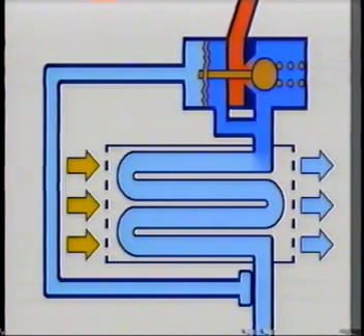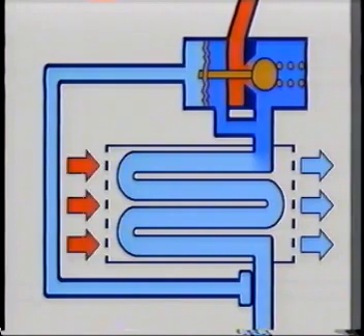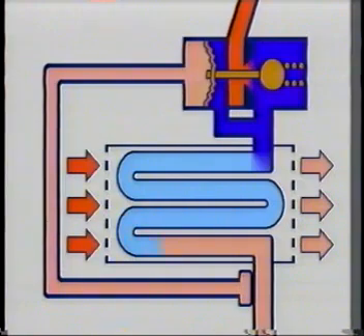When the air in the passenger compartment is hot, hot air flows through the evaporator. So the temperature of the refrigerant at the exit of the evaporator rises. The heat-sensitive tube sends a signal to the expansion valve telling it that the temperature is high. The expansion valve opens up the refrigerant passage so that a larger amount of refrigerant is permitted to flow through the evaporator.